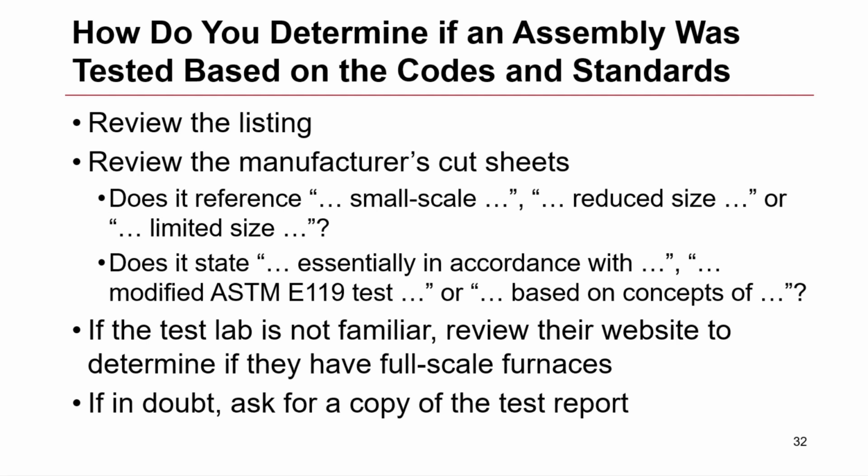And if you're looking at a UL listing, or for that matter, Intertek or FM listing, the laboratories maintain what UL calls guide information, which talks about how these assemblies are tested. So for each individual design, you can click on a link on the upper left of that design, and it takes you to the guide. The guide will clearly specify that these assemblies were tested to ASTM E119 or UL 263, which then implies full-scale testing, fully loaded samples.